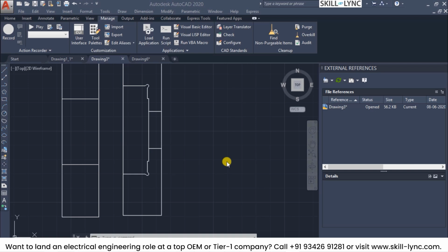The source drawings can be on the system that you work on, or on a network location, or a website, or your internal PLM software. Whatever it is, you can take it into any drawing that you work on. Even if you have multiple drawings open, you can use the Design Center to streamline the drawing process by copying and pasting content from one to the other, so that you can take all the layer definitions, the layouts, or the text styles between those drawings. We'll quickly see that now.